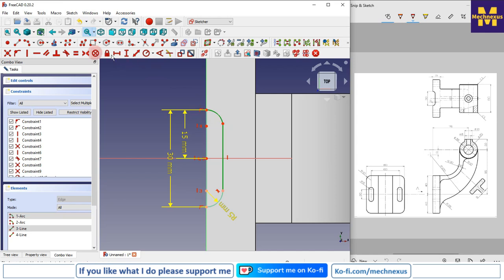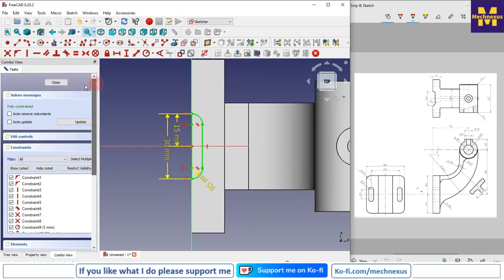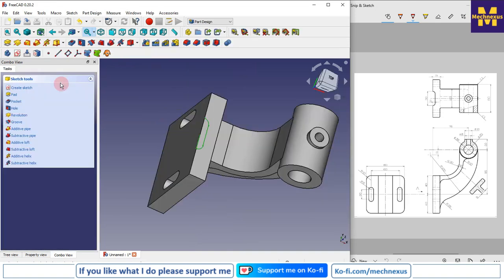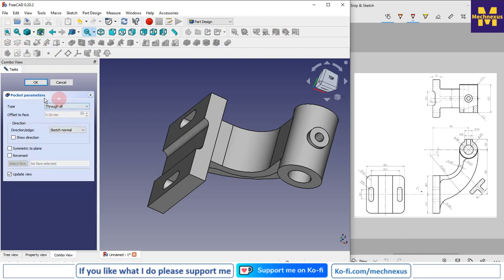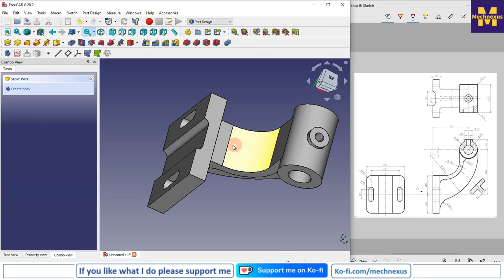And add the tangency, and I will close it and say extrude cut, and I will say through all. Say OK.